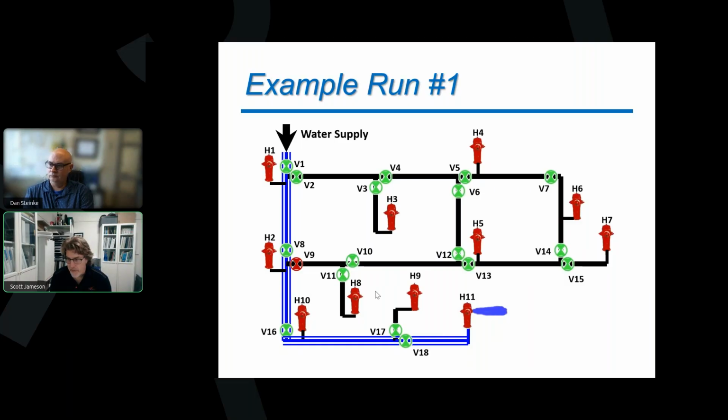So you kind of just have to visualize where the water is rushing to, and maybe with some experience you'll get a better eye for looking at it on the map. The thing I would recommend, especially the first time through, is that taking pressures at more locations is better than not taking pressures. And if you've got zones where the water seems to be rushing by, like this one here, that's something that might get flagged, and I want to take a look at.